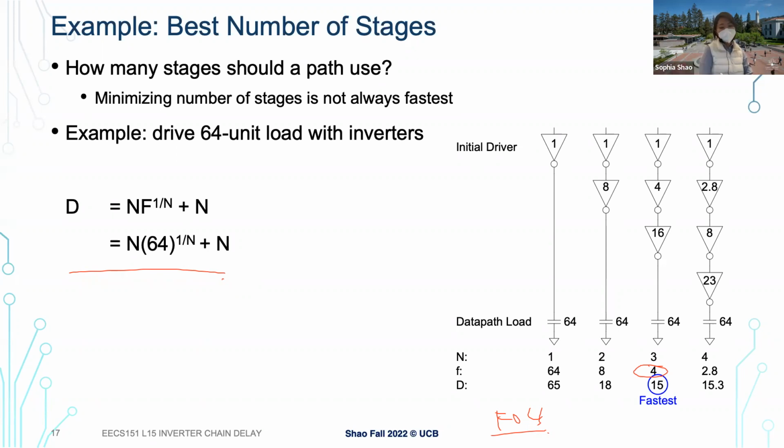And you can solve this equation. It will lead to, I forgot exactly, 3 point something, it's basically getting very close to 4 to get this balance. So that's another term you hear used to describe delay, because fan out of 4 is typically a balanced stage for each individual stage.